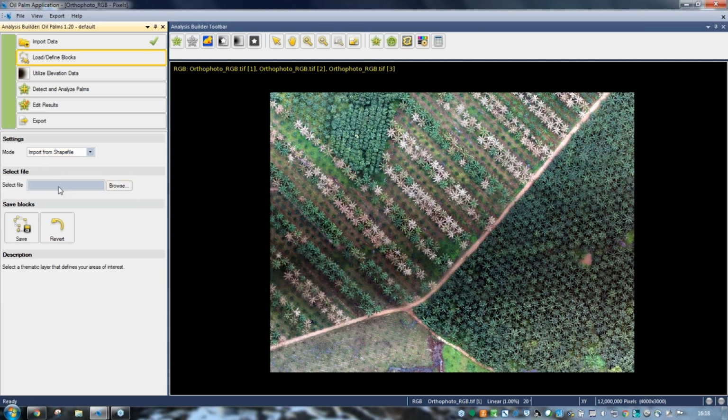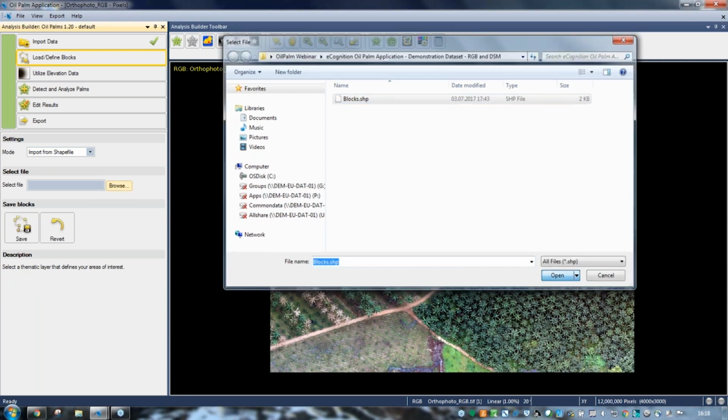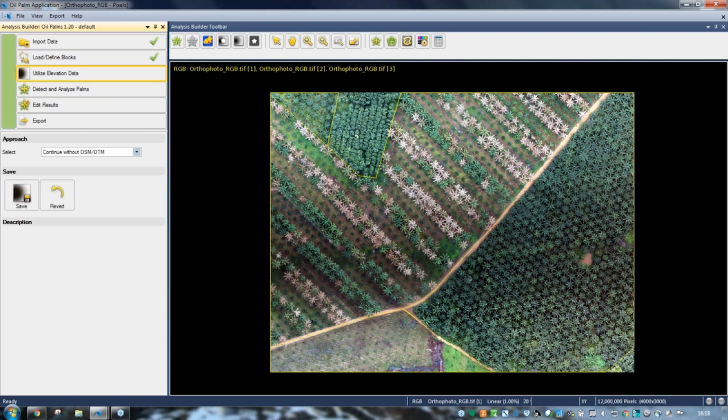The user can come down and select the data layer that they would like to add. In this case, I have some data available. I'm going to simply select the orthophoto RGB. So this is with red, green, blue bands. I'll open this. If your data has different combinations of bands, you can then come into the display settings and define whether your red, green, or blue is as 1, 2, or 3 here. This is a layer stack, so I can select which corresponds to the red, green, or blue in this portion.